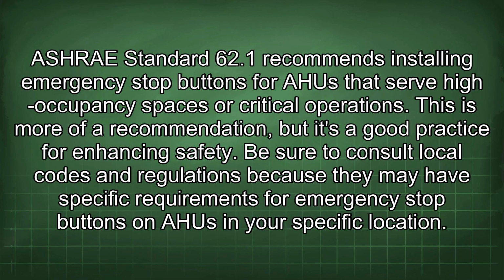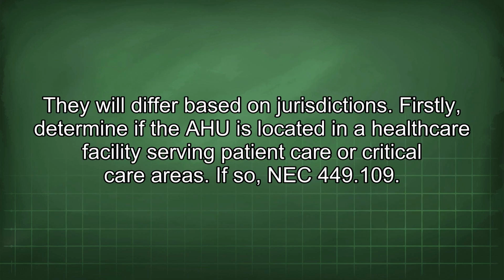ASHRAE Standard 62.1 recommends installing emergency stop buttons for AHU that serve high occupancy spaces or critical operations. This is more of a recommendation, but it's a good practice for enhancing safety. Be sure to consult local codes and regulations because they may have specific requirements for emergency stop buttons on AHU in your specific location. They will differ based on jurisdictions.